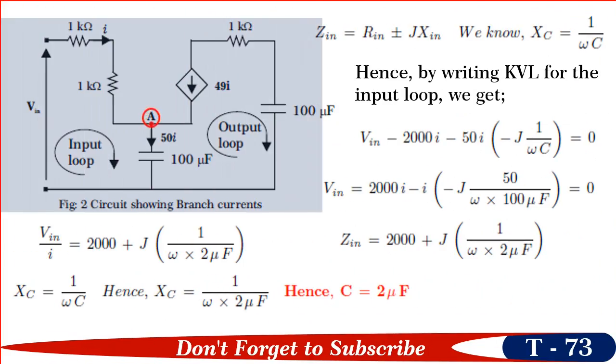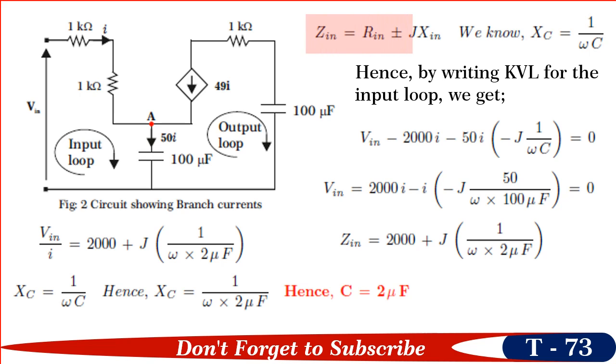By applying KCL to junction node A, we get current in 100 microfarads capacitance is 50I amperes as shown in figure. We also know that if Zin is equal to Rin plus or minus jXin, and Xin is the capacitive reactance, then X is equal to 1 upon omega C, from which we can find the capacitance C.